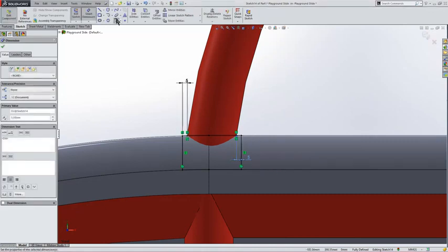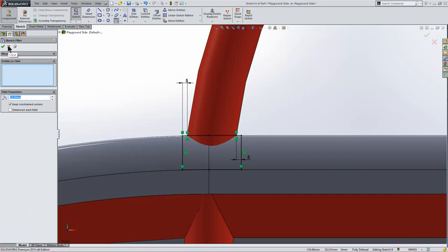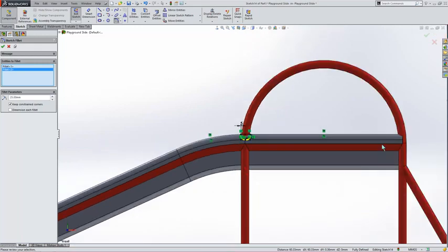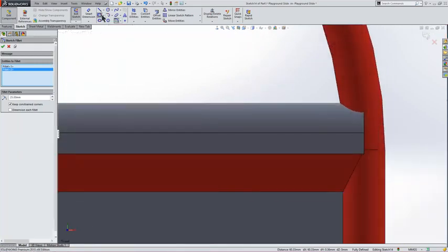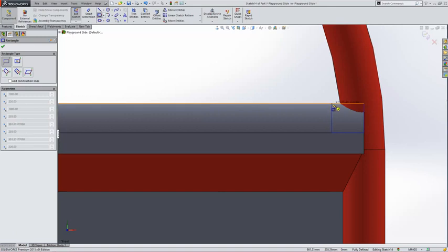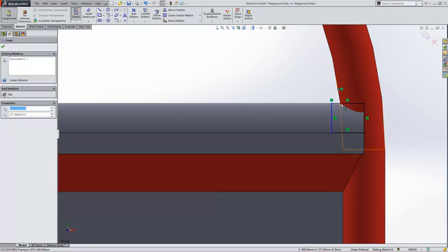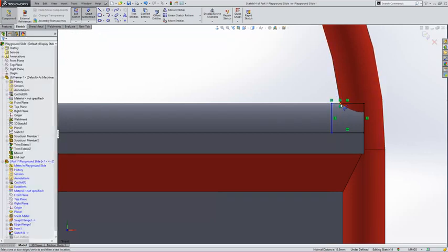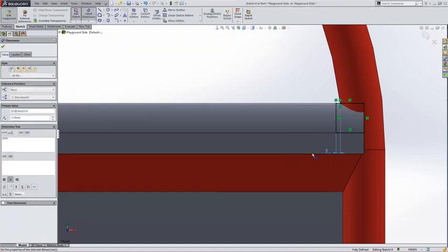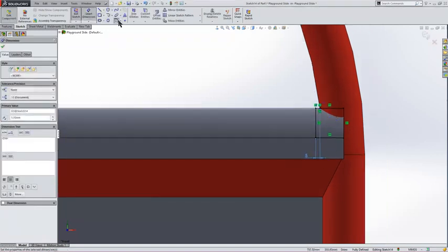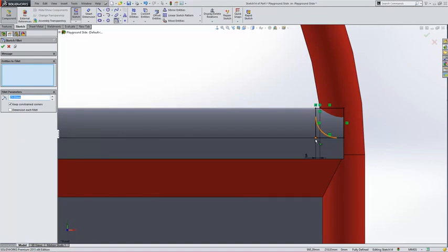Alright. We can also add a 25mm radius there on this one and that one. And we're just going to do one more at this end. So we'll grab a square, go from this point to that point there, or that edge. Same approach, and just dimension that accordingly, 5mm. This one, let's do another one, and we'll just do it on this edge here. Actually, no, we'll leave that squared off. That looks good.